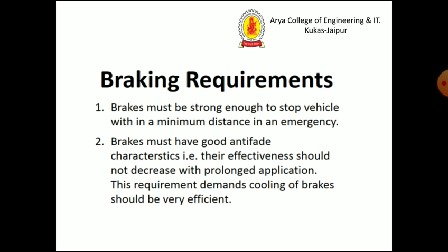Braking requirements. Brakes must be strong enough to stop the vehicle within a minimum distance in an emergency, and the brakes must have good anti-fade characteristics, meaning their effectiveness should not decrease with prolonged application. These requirements demand that the cooling of the brake should be very efficient.